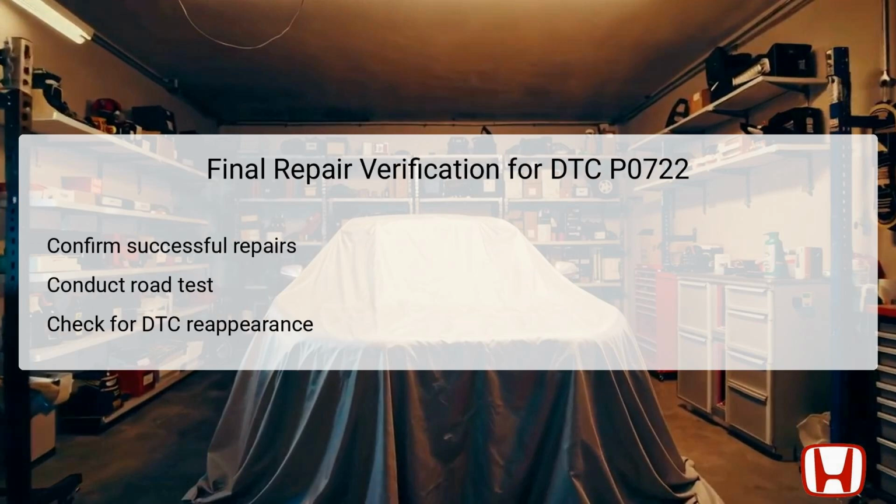Once all necessary repairs have been completed for the DTC P0722, it is crucial to verify their effectiveness through a structured, final repair verification process. Begin by clearing any DTC codes from the vehicle's system to reset diagnostic functions. After performing repairs, taking the vehicle for a road test is essential to monitor its performance under real-world conditions.